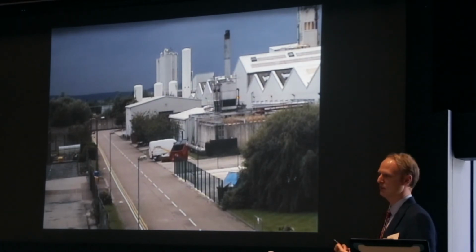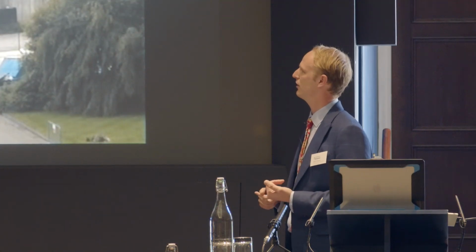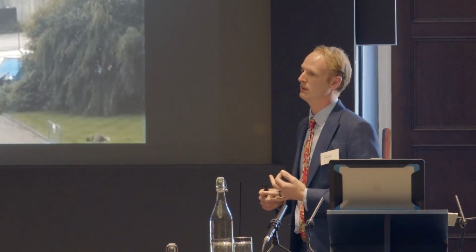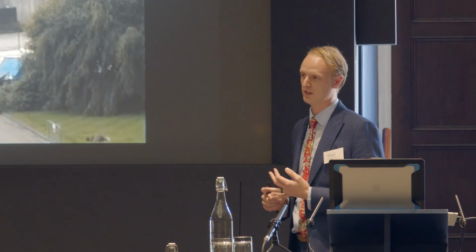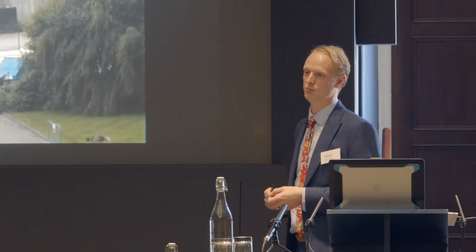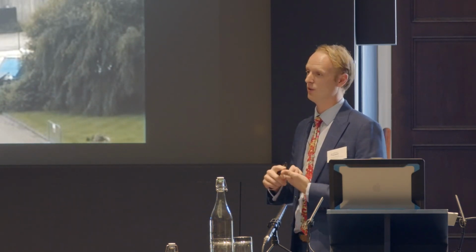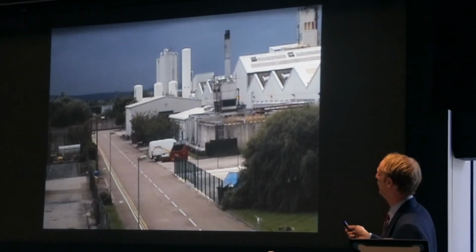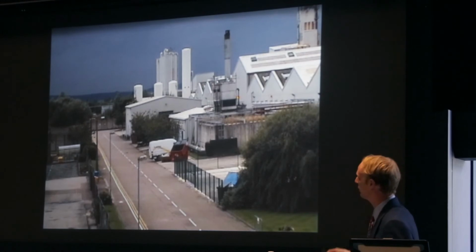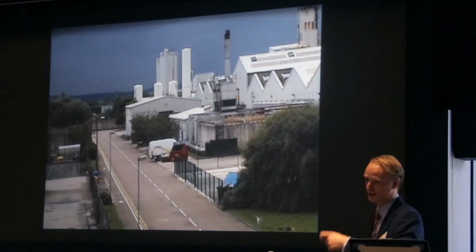So if you think, many fans run between 900 and 3,000 RPM. So that when that fan, if it fails and it lets go, as we call it, it can fly off at between 100 and 300 mile an hour when it flies off. In this instance, we've got a fan that's about 1.5 metre in diameter, the blade that comes off.